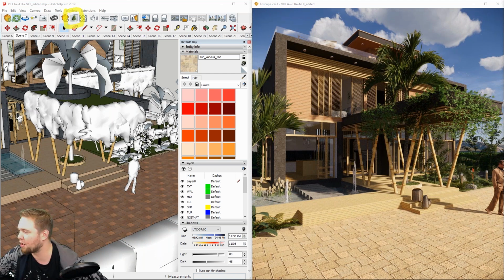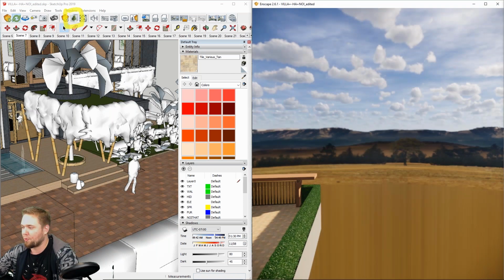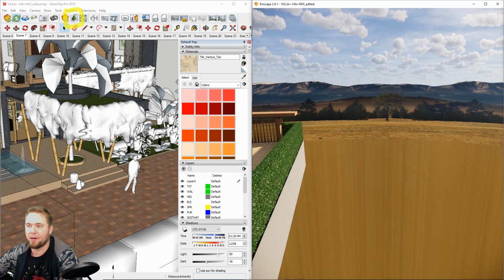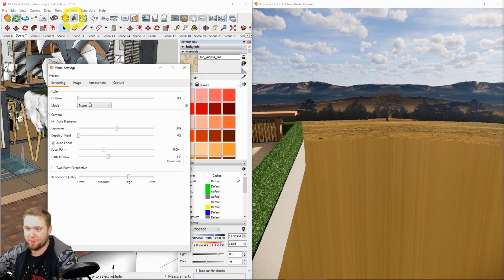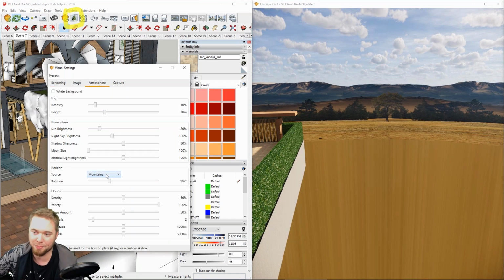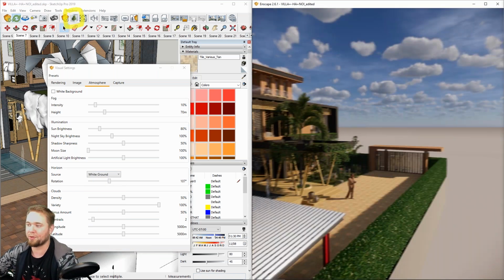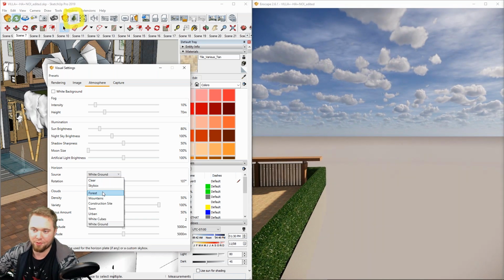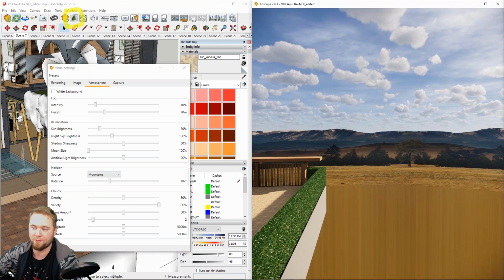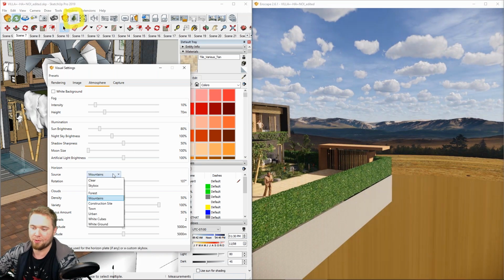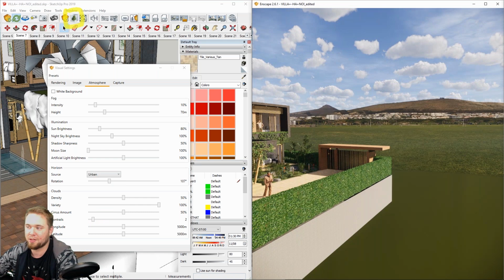How about a ground plane / horizon option? So there is the giant hole beneath all projects. Melissa, so we do have a ground plane / horizon option. You find it in the Enscape settings atmosphere tab. You can choose, well, if you want to have a white ground or a black ground, or you can go for one of our skyboxes, or for one of our horizon presets, or for your own skyboxes.